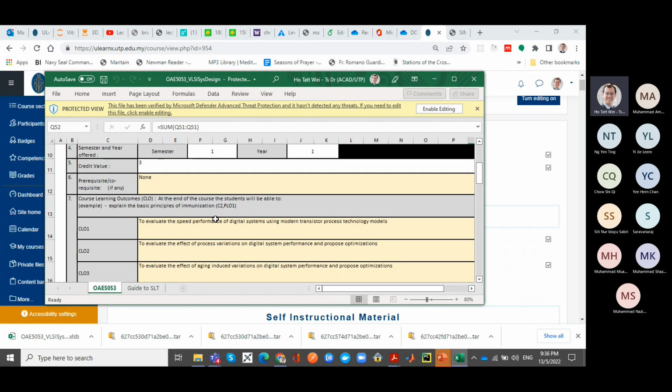There are a lot of tricks being played to get the lithographic process to match that, but it's not foolproof, it's not 100%. So the main limiter of performance nowadays is what we call process variations. You have the same integrated circuit design and you make 20 of the same chips. All 20 chips are not going to be exactly the same; they're going to have different performance. So how do we analyze that? How do we take into account the effect of process variations, specifically how they impact speed performance?